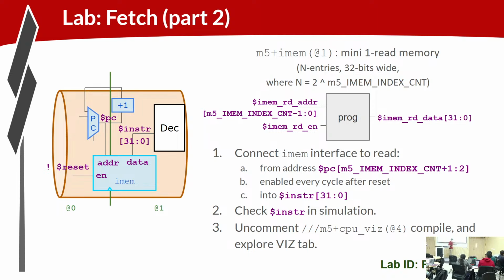There was some remaining confusion about ignoring the 2 bits, the byte-oriented addressing, right? In terms of the PC, the PC is a byte address. So when the PC is referencing a particular instruction, it's referencing it by this address. The first instruction, it would be referencing address 0. The second instruction, it would be referencing with address 4, etc. If the PC for some reason is misaligned, so we try to access address 5, we should get a misalignment error. The CPU should go nuts.